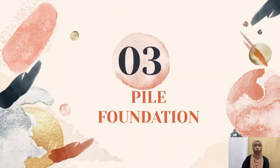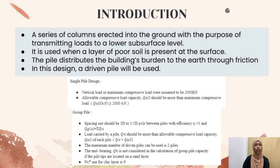The third scope of work is pile foundation. Pile foundation is described as a series of columns erected or put into the ground with the purpose of transmitting loads to a lower subsurface level. It is used when a layer of poor soil is present at the surface. The pile distributes the building's burden to the earth through friction. So in this design, a driven pile will be used. The design criteria is divided into two types, which are single pile design and group pile design.